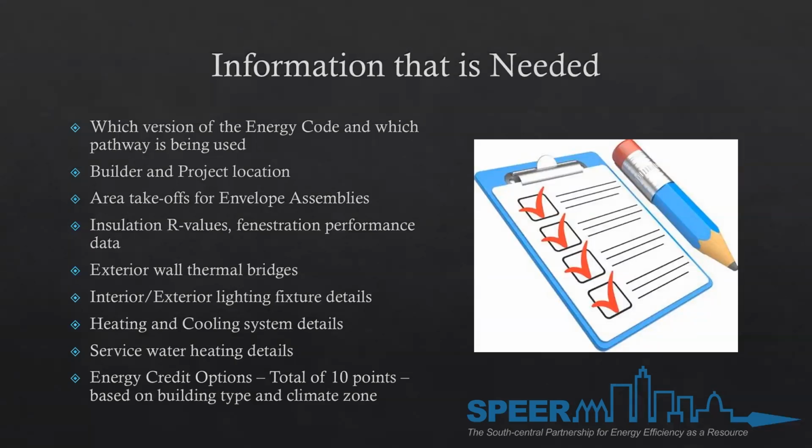fenestration performance data is also needed. Of course, exterior wall thermal bridges, interior and exterior lighting details, fixture base details. How many fixtures of each do you have? What's the wattage for each fixture? Heating and cooling system details. One more that we'll see when we get to the live version, it digs down even more, is fan efficacy.